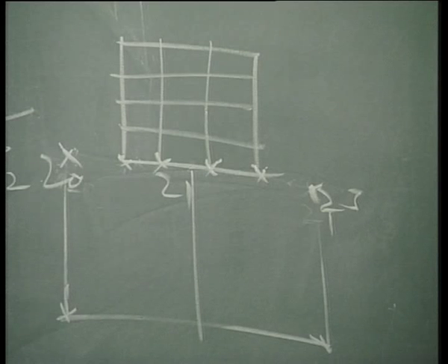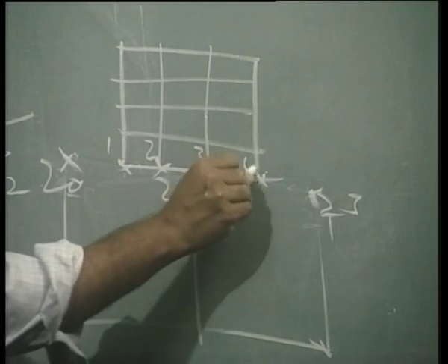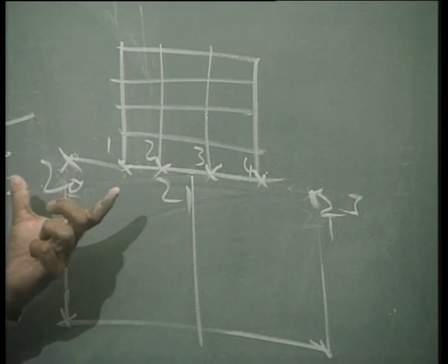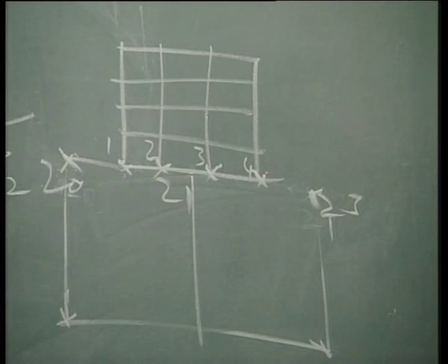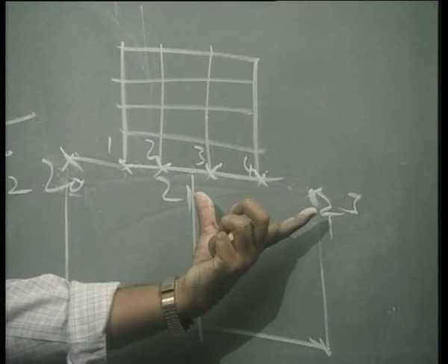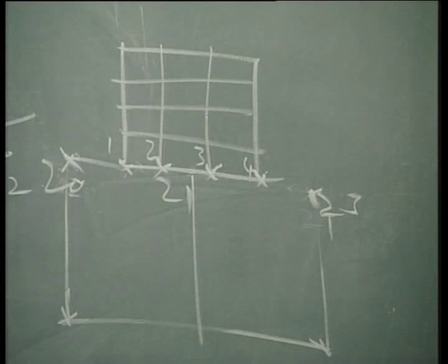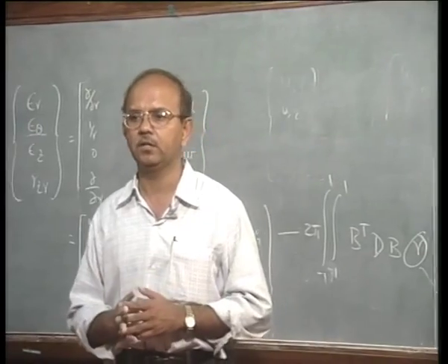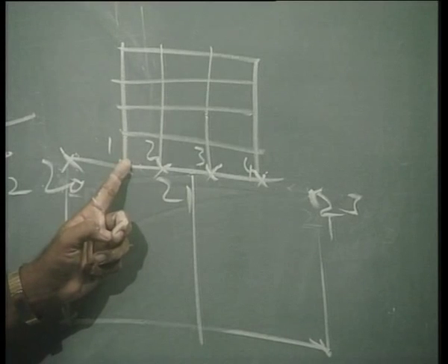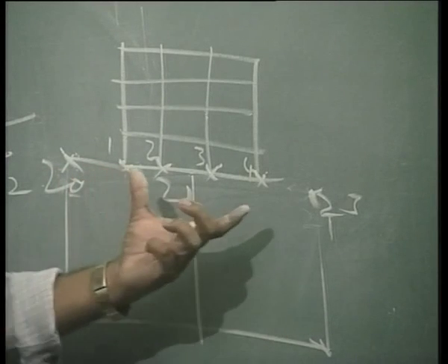One of the jobs of the algorithm in any of the softwares that you may use is to find out whether these nodes, say 1, 2, 3, 4, sit or come under the influence of which of the master segments. There are now 2 master segments, remember that, 20, 21 and 21, 23. In software they call this the contact searching algorithm. So, the contact searching algorithm will find out whether 1 sits in 2021 or in 2123.